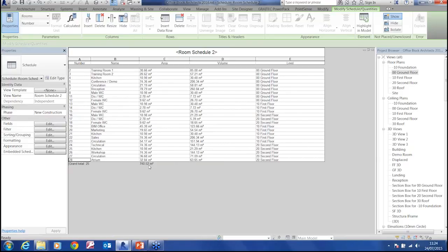Now, it may be that I've been given a spec and I've got certain requirements that I've got to go for. So imagine you've been asked to design a school. You might know that that school needs 12, 24, whatever classrooms. Each classroom needs to hold 30 students and 2 teachers, 2 teaching staff. Then we can work out exactly how big the minimum requirement is for the area for that space.